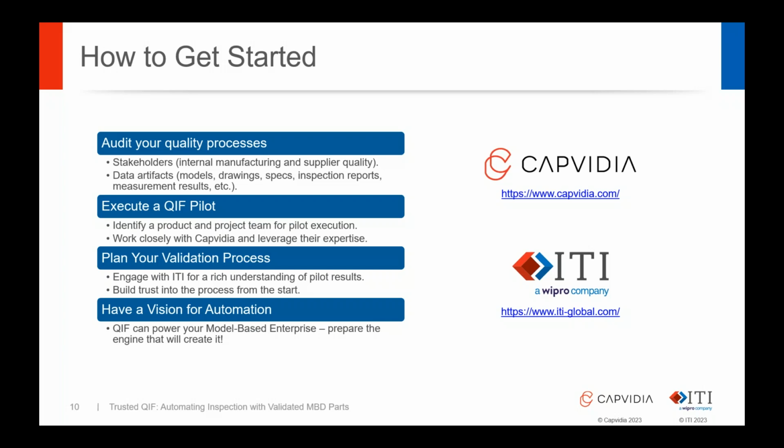And then I think the biggest thing, which I did touch on briefly, is the idea of collecting as-built product data, or by the way, it could be process data as well, telemetry data from certain process tools, and linking that back to the model, establishing that digital thread from as-designed to as-built. So those are some of the other areas that you see with QIF, especially with MBD. But really, honestly, anything's on the table.